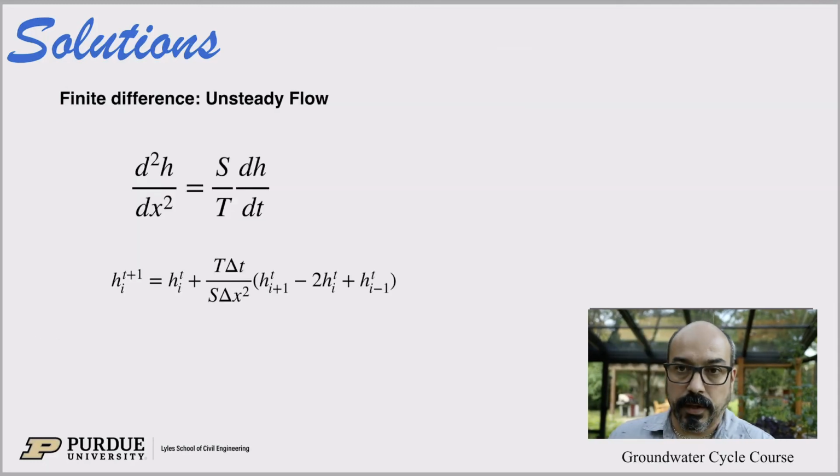Now, for unsteady flow, I'm just making a note here because we haven't talked about unsteady flows much at all. But when you do pumping, that is all about unsteady flow, because when you start pumping you're dropping the water table, or piezometric head, down, and if you stop pumping it goes back up. So really the time evolution of the water table is what tells you the transmissivity of the aquifer, and tells you a lot of information. So well tests are in essence unsteady.